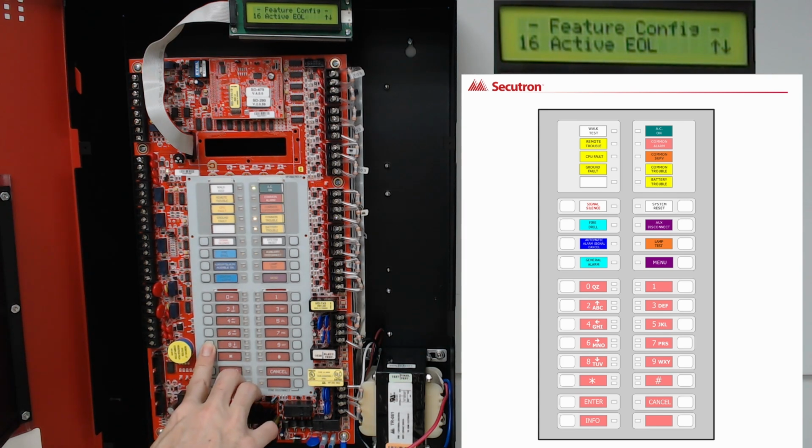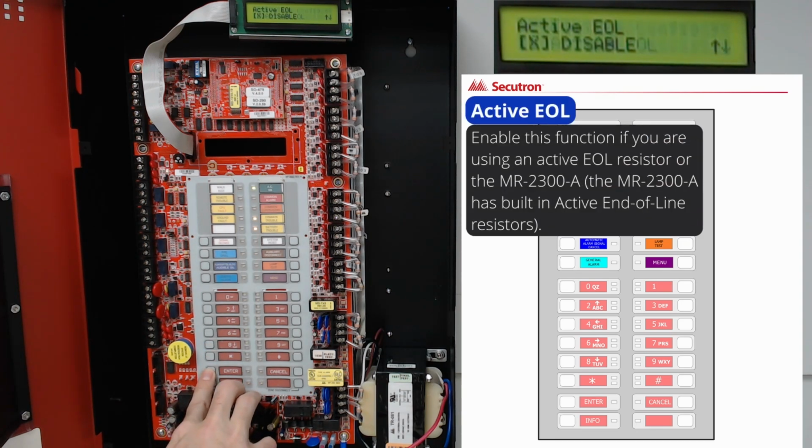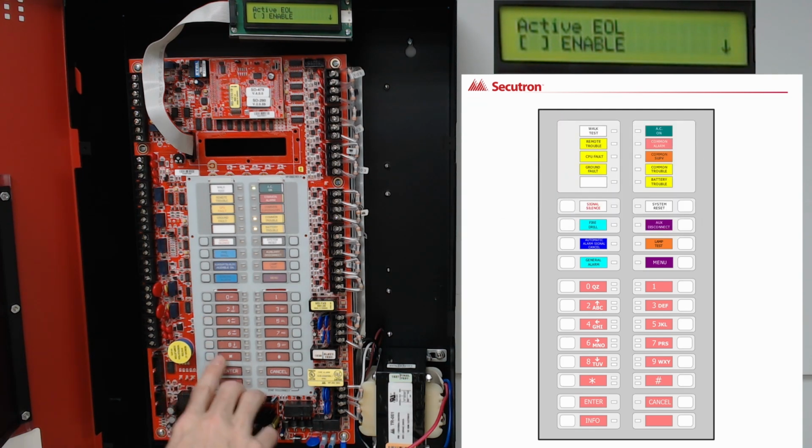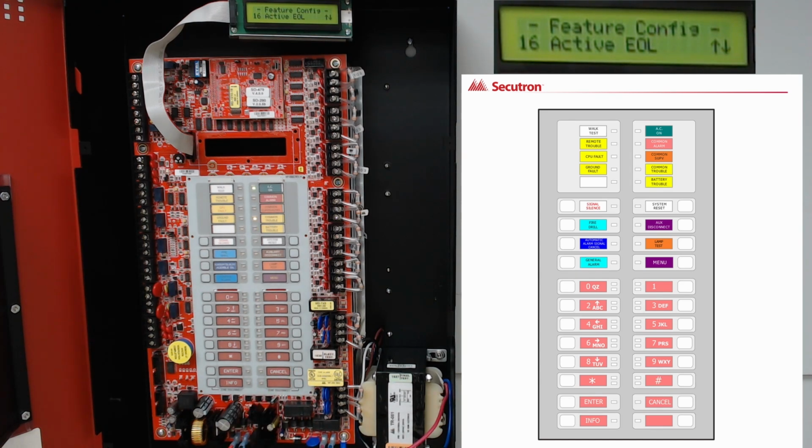The next option in Feature Config is Active End of Line Resistor. By pressing Enter, we get to see the options for it. By default, it has been disabled. However, if we press the up cursor, we can enable it by applying the X by hitting the left or right cursor arrows, if we choose to. By hitting Cancel, we exit back out to the previous menu options.